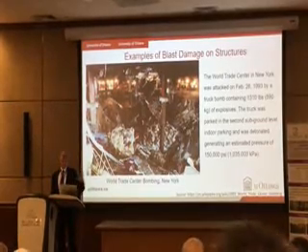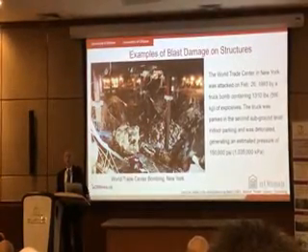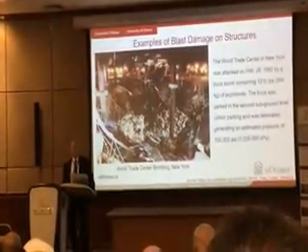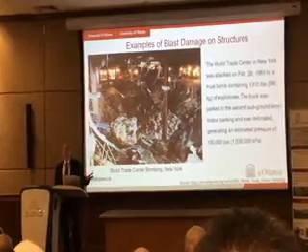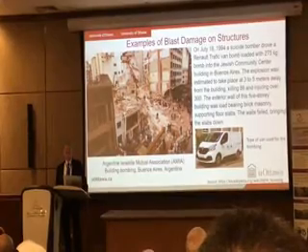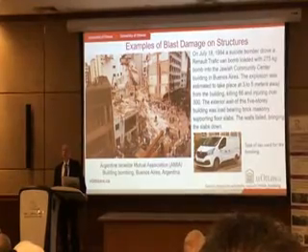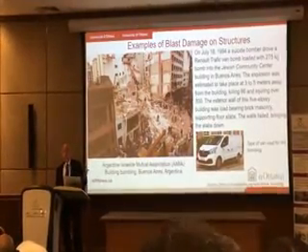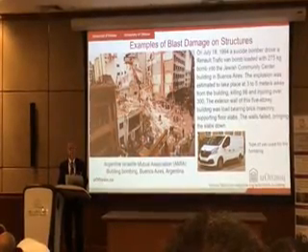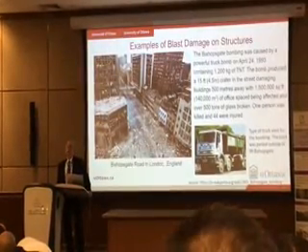So these are all external attacks, but then there could be attacks from within, in the parking garage, and here's an example of the World Trade Center attack in New York City in 1993. It did cause collapse of the slabs, and it triggered some failure. And elsewhere in the world, in Argentina, there was an attack. This time, it was an attack on a community center, and it brought down masonry walls. So we will look at reinforced concrete columns, reinforced concrete panels, and masonry walls. And we cannot dismiss non-structural elements.